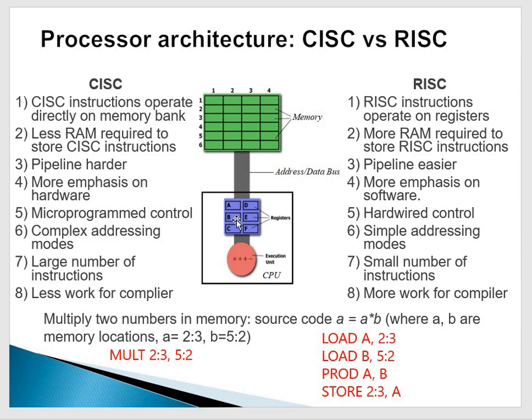This is the basic difference. The instructions of the CISC can access the data directly from the memory and manipulate it. But on the other hand, in case of RISC, the instructions can manipulate the data or perform the computing operations only on the registers. So before we start to perform any arithmetic and logical operation, we will have to load the data from the memory by using the different instructions which can be used to load the data from the external memory.